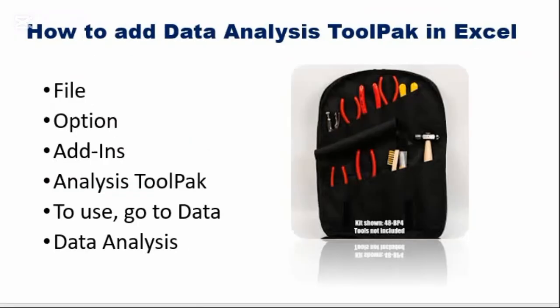Now, coming to do this in Excel, many Excel installations do not come with the inbuilt statistical tools needed for this analysis. So usually we add it in. If you have not used it before in your Excel, you need to add it, and to add it is simple. You go to File in Excel, go to Options, go to Add-ins, and then click Analysis ToolPak. That will appear. I'll show you how to do that.